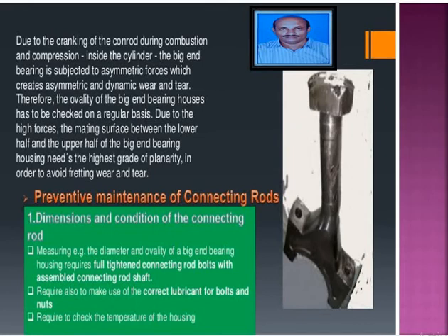Okay, already we are drilling holes on the connecting rod, and for the tightening nuts and bolts also we have to use lubrication on these connecting rods. Another thing is that we are required to check the temperature of the housing. Whatever temperature rise occurs, we have to check it.